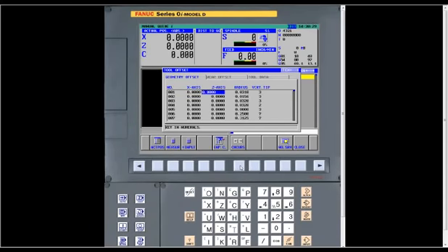Now we'll change the cursor as we page over. The next value that we need to fill out is the radius. And what that's asking for on a turning tool is the radius of the actual insert. I know on my tool, this is an 80-degree rough turning insert. I'm using a 31 thousandths nose radius tool. And where I get that number from, let's do this.